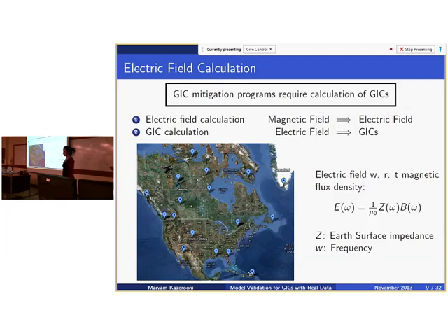But a lot of the transformers that are most at risk are the ones at the generator. You put those in place because you're going to operate them at maximum load. So usually you don't. It's on the GSUs that you have the most trouble, and normally they're heavily loaded. You could back down the generation to reduce the loading on those transformers. So there are operational mitigations that can help out.